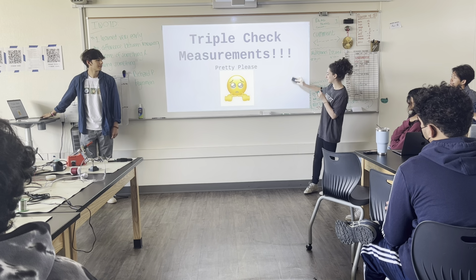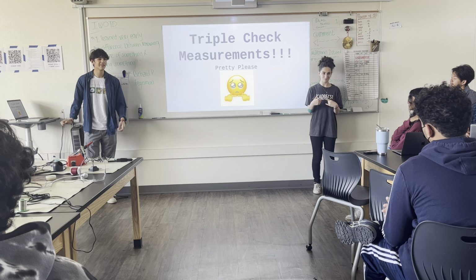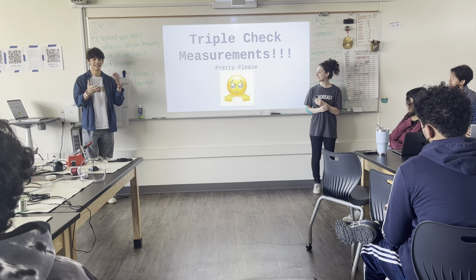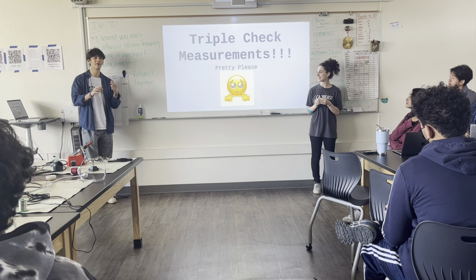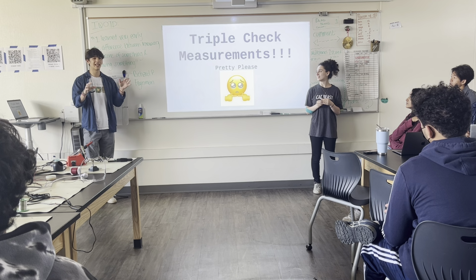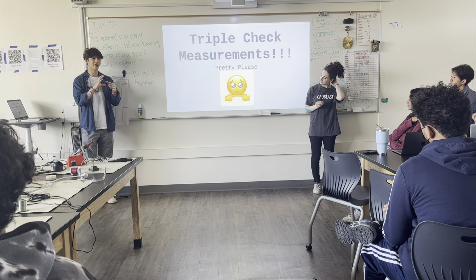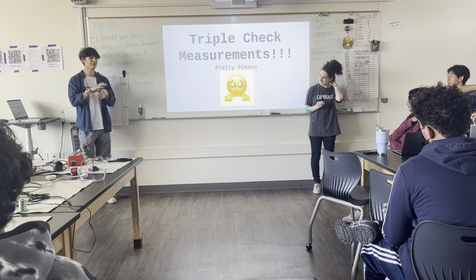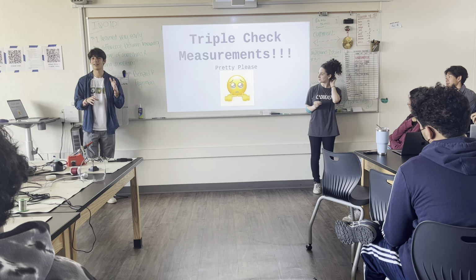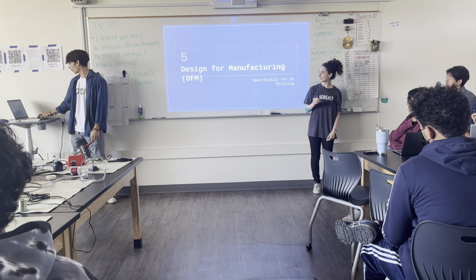Please triple check your measurements. Yeah, so another thing is if you have a part that needs to slide into another part, make sure that your measurement isn't just anywhere, but it's your largest measurement, the largest size that needs to fit into a part. Make sure that that's allotted for.